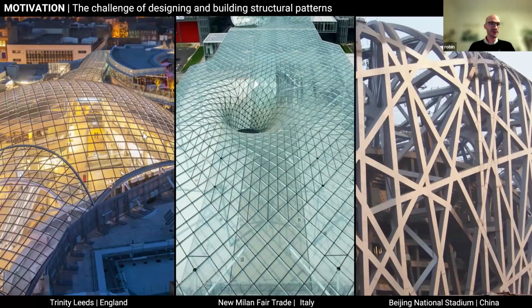Here on the left, you can see this regular grid. That's nice because you only get flat panels, so flat quads for the panels in glass that are cheaper, but it doesn't take into account the boundary conditions of the support. So you can see here that along the edge it's just been trimmed. So there's not an efficient load path towards the support. You have these awkward elements that need to be detailed with these triangles or pentagons. So here the boundary conditions, the support conditions, are not taken into account, which is key when it comes to mechanical efficiency.